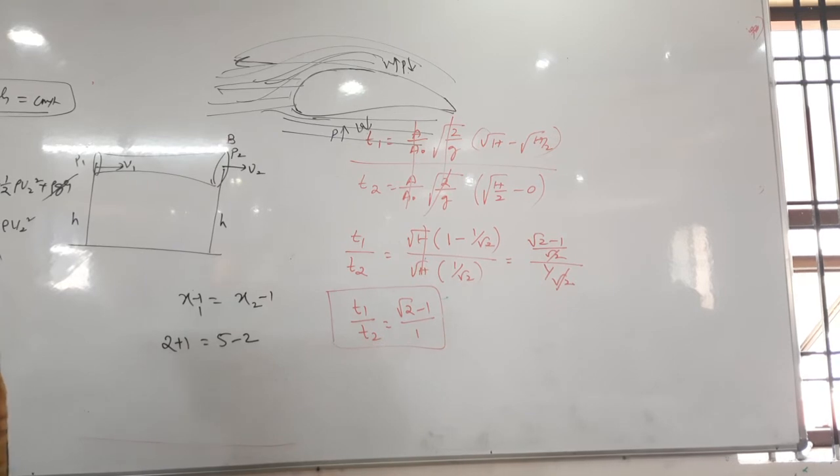Onto the top it is coming, due to this structure of the wing, more air will come onto the top and less air will go on the bottom. More air coming means there is more velocity of the air. More velocity means pressure will be less, and here velocity will be less and pressure will be more. Here more pressure is acting from the bottom to top and less pressure is acting from the top to bottom. So wherever more pressure is there, in that direction only it will move obviously. Clear? That is how the dynamic lift will work.